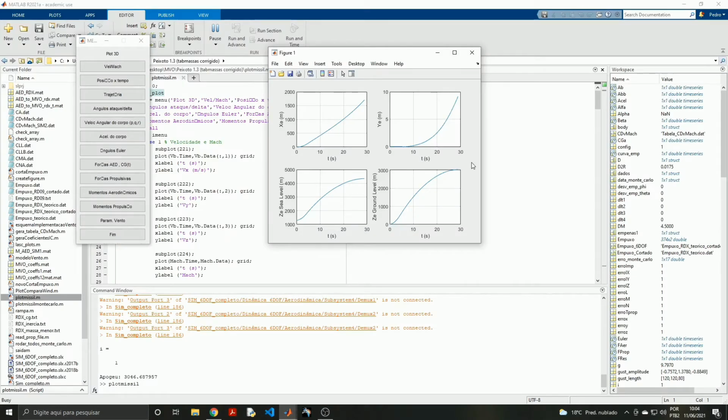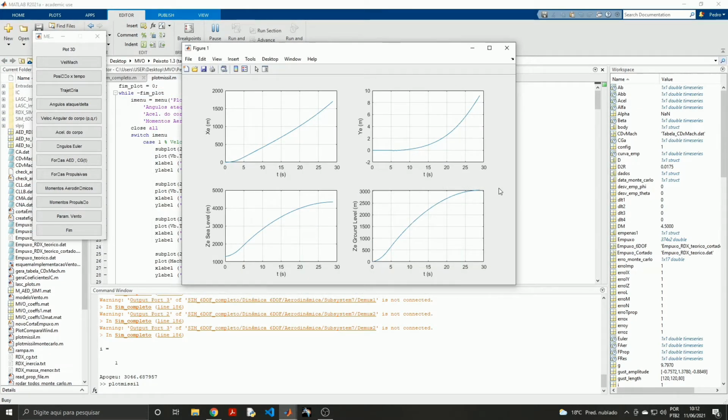After executing the simulation, we are ready to gather relevant data. In addition to data required by the other subsystems, such as the maximum Mach number and the maximum acceleration, we must verify competition requirements, such as the apogee and stability on rail departure. The predicted flight apogee falls very near to the target apogee of 10,000 feet or 3,000 meters above ground level.